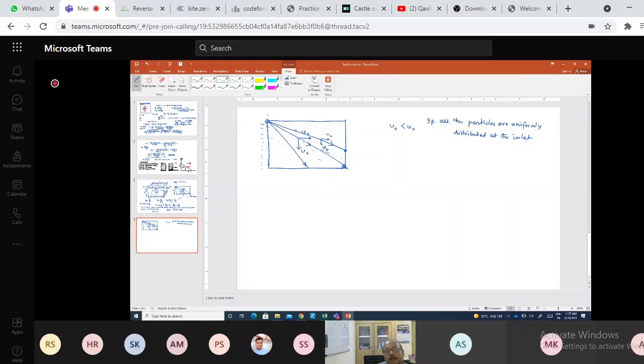If I draw parallel lines to this one, they will follow this trajectory. So you can see that if I draw a parallel line to this, which meets here, then the particle which is introduced at a depth, let's say small h, and below, will all be trapped.